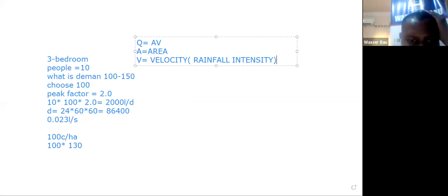Catchment B will now be, this is the volume for catchment B, but the flow at catchment B becomes A plus B. This plus this gives you this. Catchment C is on its own, so it remains this, after multiplying by this.